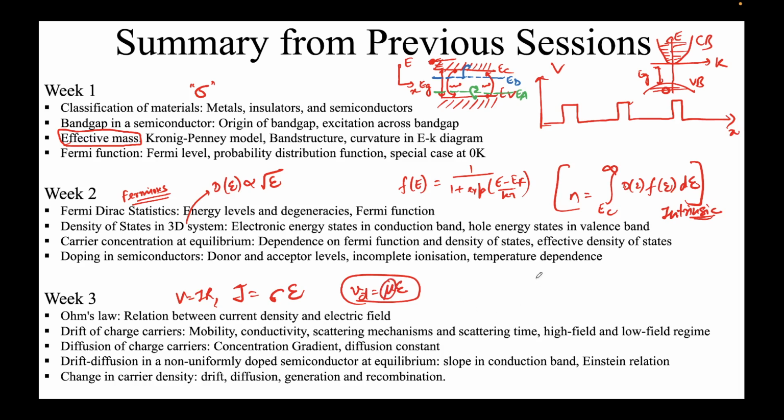This is the low field regime. So when we drew drift velocity versus electric field E, it looks something like this. In the linear region, Vd is mu E. Mu is the mobility, as I'm saying. And we also saw different scattering mechanisms, like due to the lattice, due to Coulombic interactions, phonon interactions, and so on, right? And the other transport mechanism is diffusion.